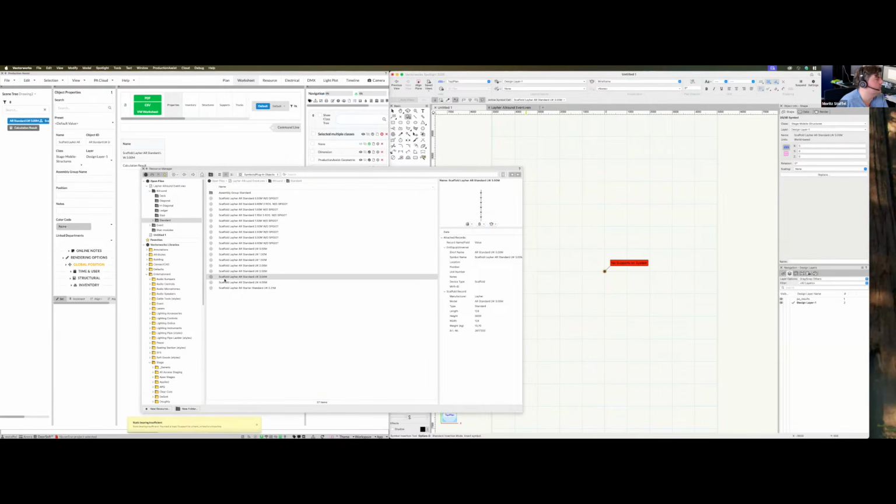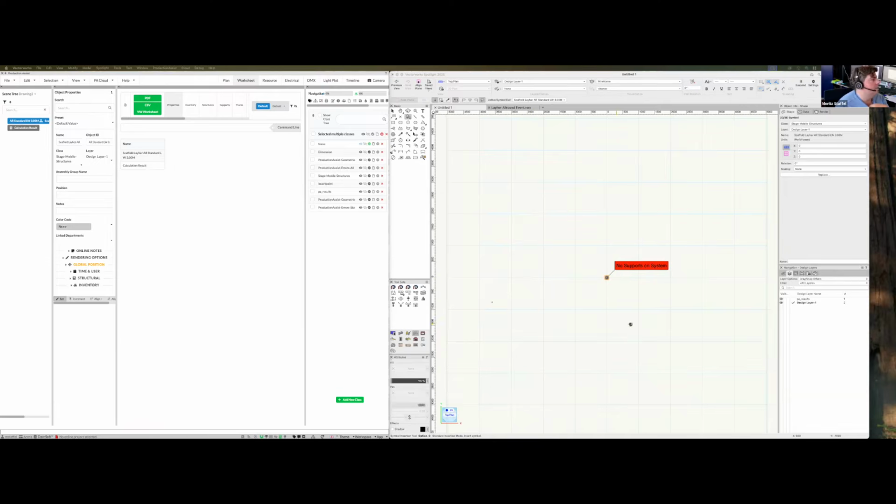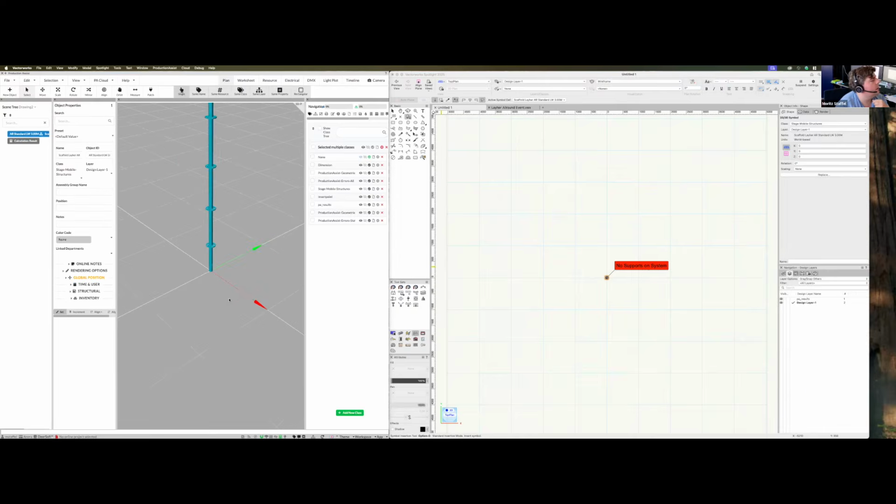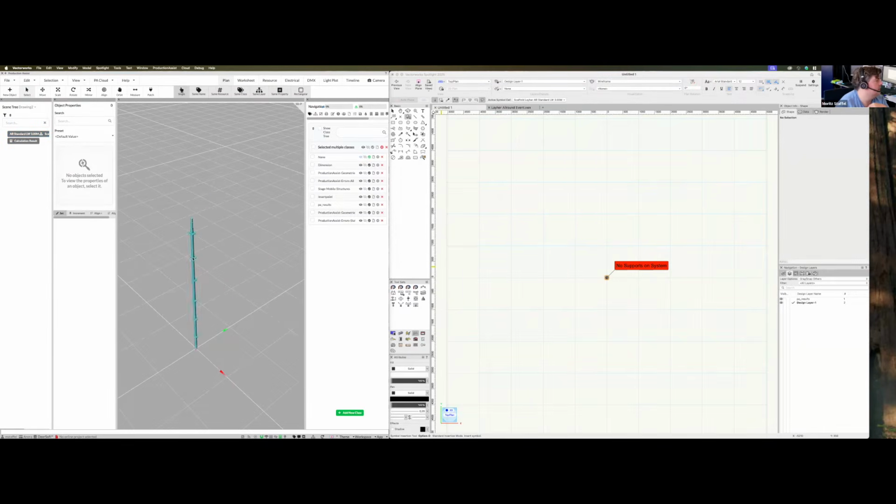But you see, once you've placed the layer scaffolding in here, it immediately tells you that it is not supported. So there is no connection on this that actually supports this, which is not a big thing for us. We will do this a little bit in the process. I just move the scaffolding a little bit to the side. I change this to the plan view, and now I see the ledger and the standard, so that it goes up.